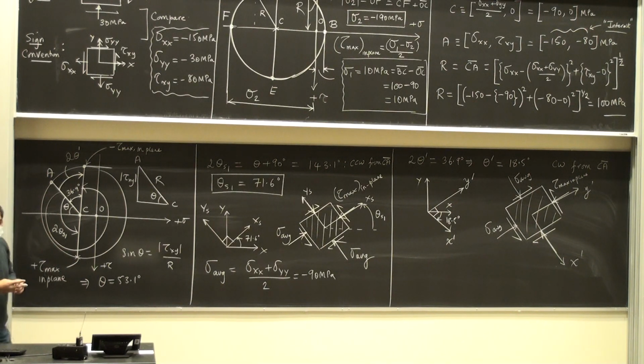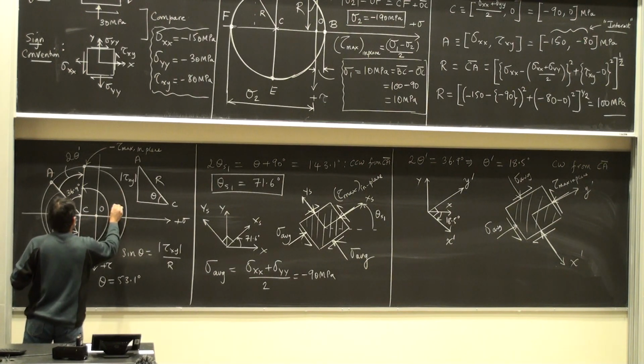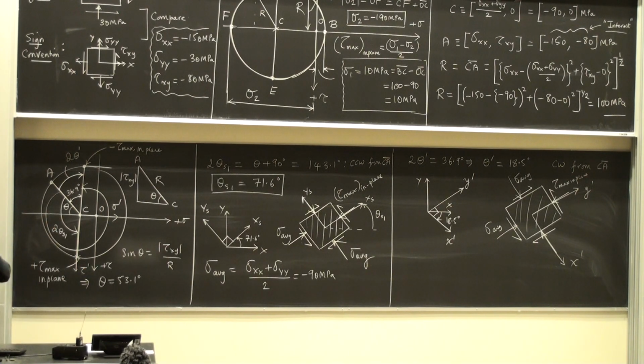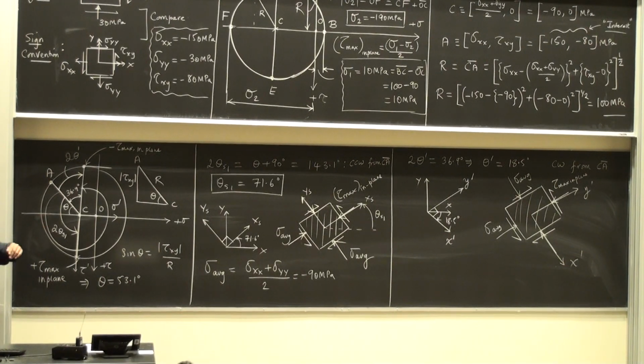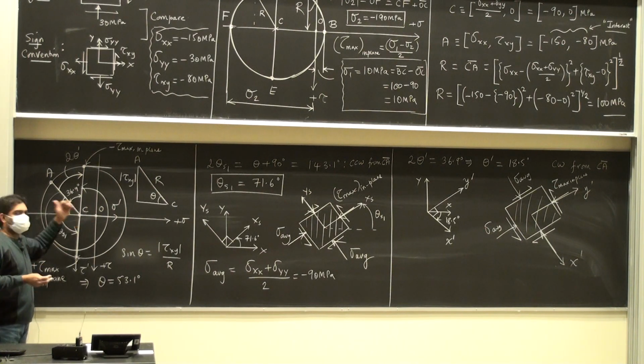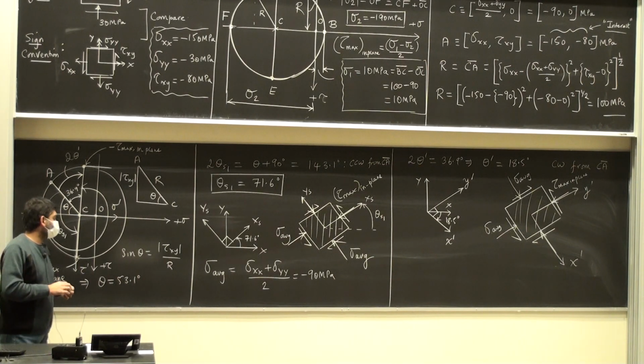Yeah, I'm sorry, I said axis, I meant origin. Do you have the freedom to move it? You could. I mean, you would have to do a change of axes. I can have a new set of axes which I start from here called sigma prime and tau prime. Is that what you're talking about? Yeah, you'll have to do a coordinate transformation, which means everything will have to be shifted by 10 megapascals. But it's not worth the effort, right? Because you already know that your origin is sitting here. So you can do it, obviously.